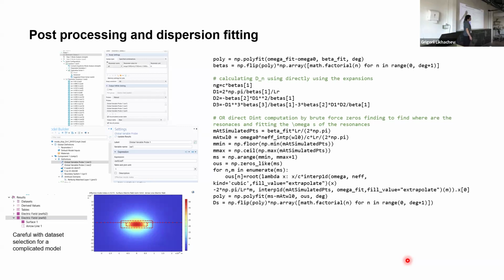You have the variables that you can define in the table that I showed before, and then you can do sweeps automatically. You can either save all the modes you have been solving for, or only save some parameters derived for you by using the so-called variable probe feature. This can reduce your file size a lot if you don't need to save all the parameters, the full field simulation. You only need to save, for example, the effective index, and you don't need to save all this, but only the value calculated by the probe. Only save that.